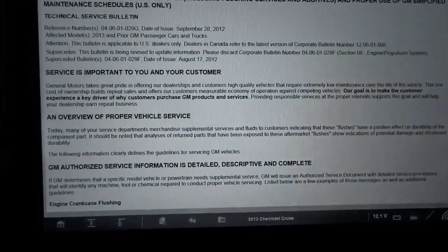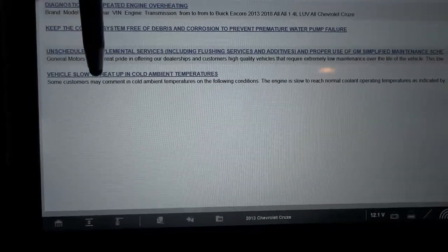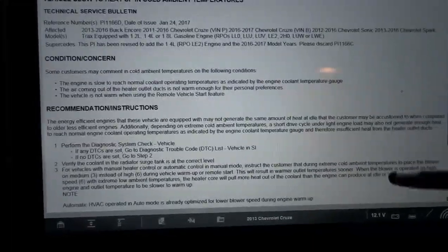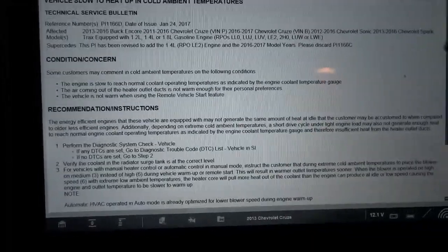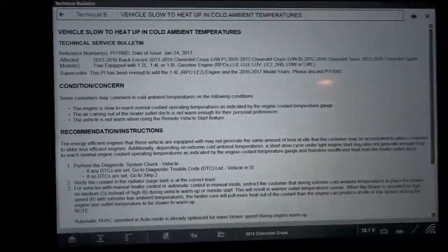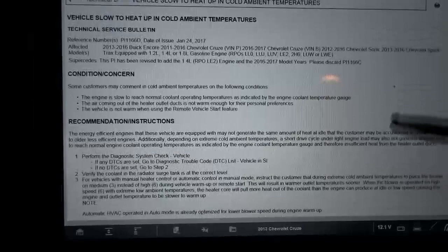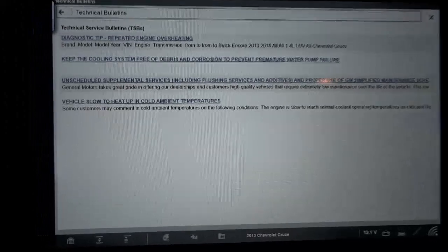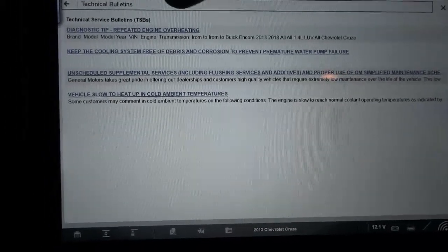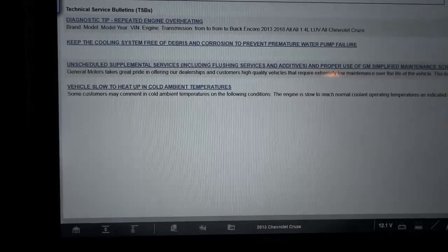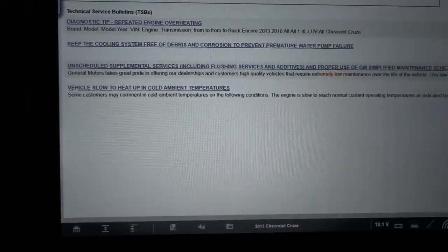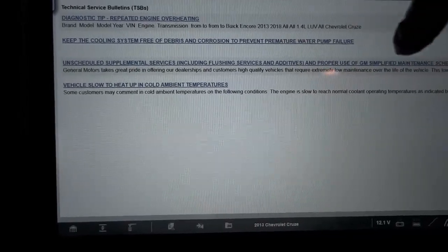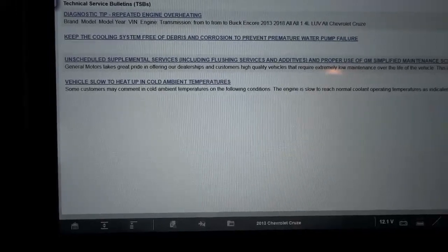Okay, well, and again, guys, when you diagnose any trouble code, it's always good to be informed. You want to read and know and gather as much information as you can. That will help you determine the right course of action. So basically, with all the TSBs we read, the first one talked about the surge tank, I mean the reservoir, the cap, and then the other one about the debris in the cooling system. We know the water pump was replaced. This one is suggesting doing a cooling system flush.